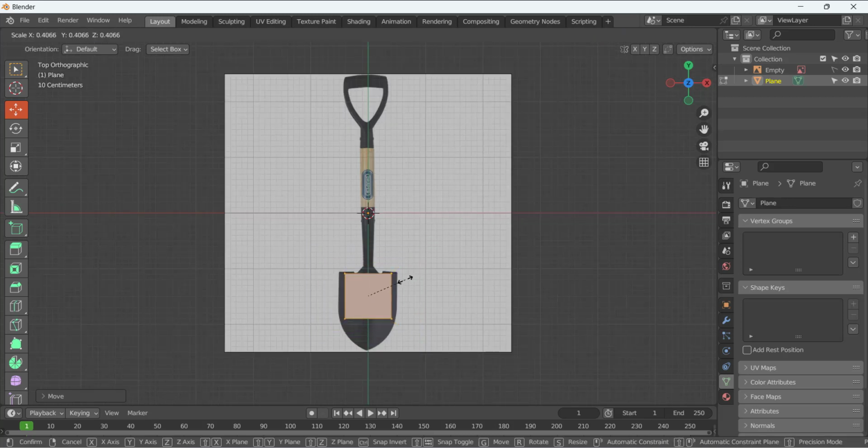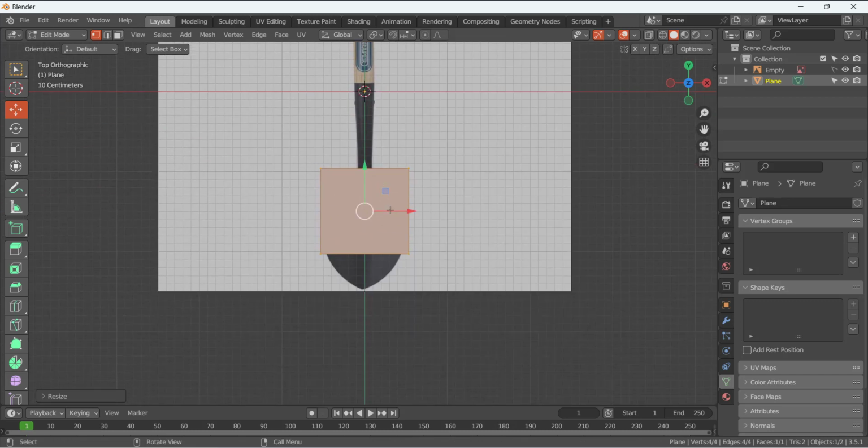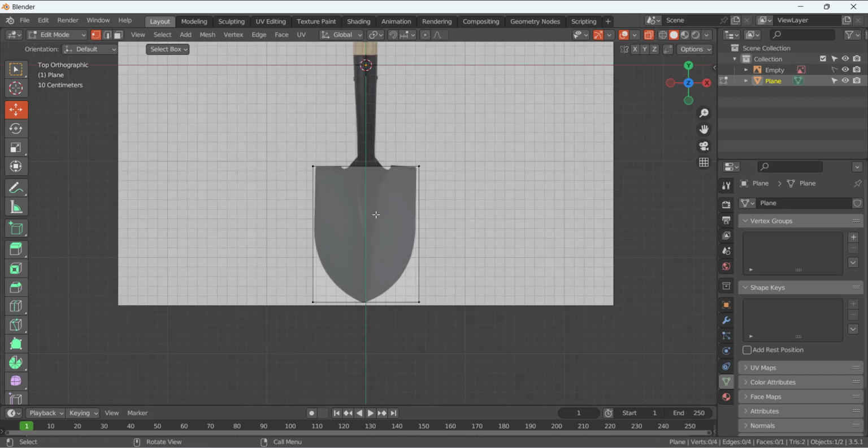its topology. So I am going to make it like that, scale by using S, and select these two vertices, and here I am going to activate the toggle X-ray view and select these two vertices and move it like that at this point, and these two, select them and move it like that. And here I am going to add a loop in the center, so Control R to add a loop and place it in its initial position, so it's in the middle.